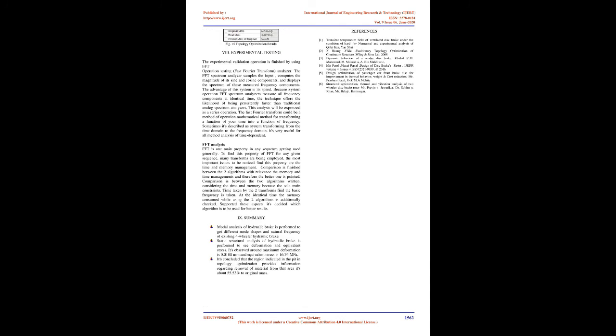8. Experimental testing. The experimental validation is done by using FFT, the fast Fourier transform analyzer. The FFT spectrum analyzer samples the input, computes the magnitude of its sine and cosine components, and displays the spectrum of these measured frequency components.